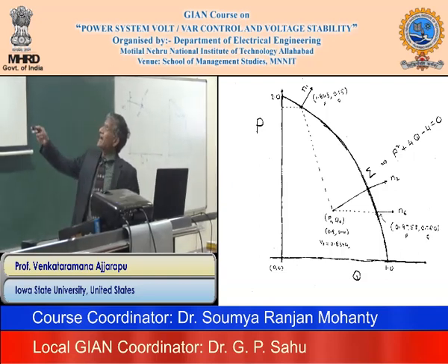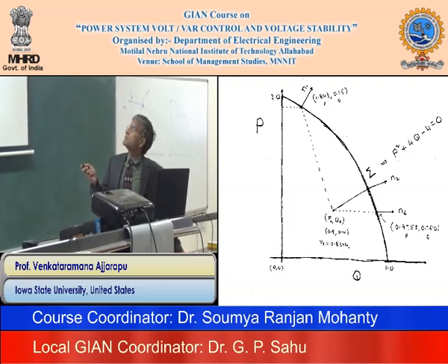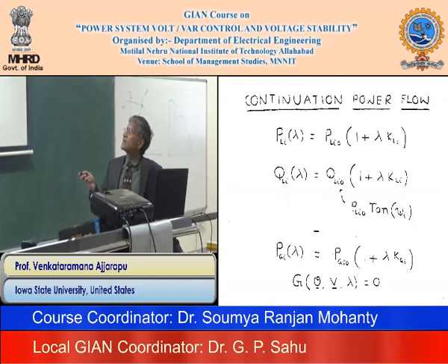We know the PLi, the load power at a bus i, and reactive power at bus i, and I'm putting lambda because I'm changing the lambda. So you can represent that as PLi0 plus lambda times KLi, right?